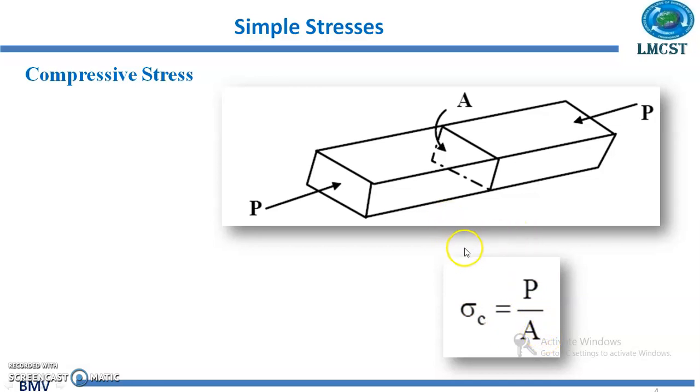Now we always have to remember that if we are applying a force whose magnitude is in newtons and the area of cross section is in millimeter square, that is, the sides are expressed in millimeters, then the unit of stress is Newton per millimeter square.